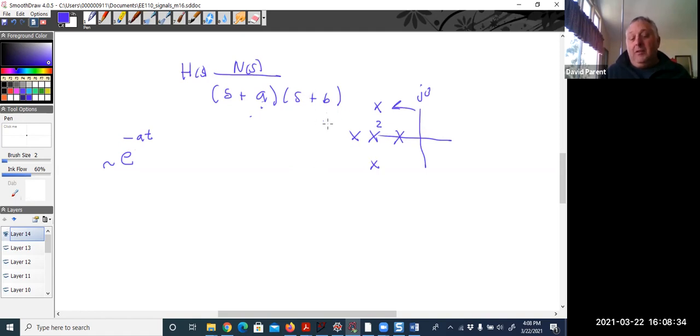We're going to talk about what happens when, essentially, if I put in an impulse, no matter what, it's going to stabilize to some value. A low pass is going to stabilize at a DC value. A high pass is going to stabilize at 0. A band pass will stabilize at 0, and a notch will stabilize at a DC value, but it stops.